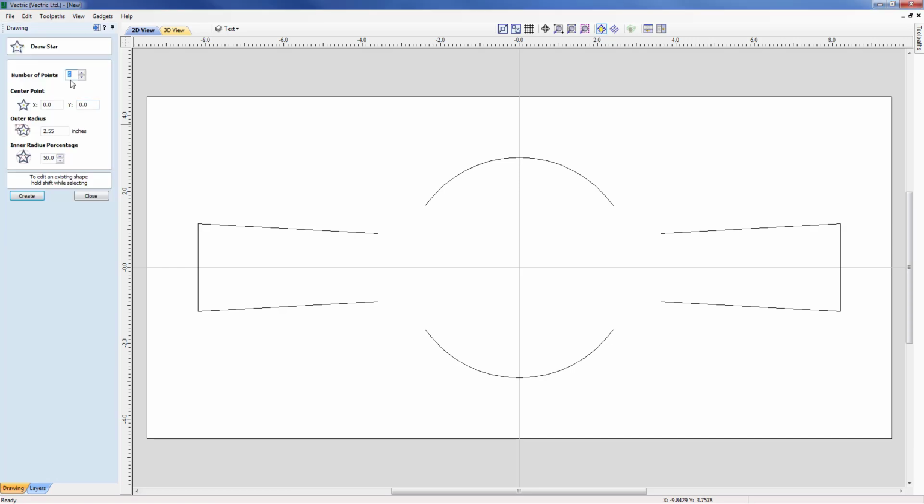We're presented with a form where I can add the parameters, or I'm just going to go to the screen, left mouse key, and just grow the arc now and just drop it in that position. Come across to the form, which now has those values, and I'm going to specify just a smaller outer radius of just 0.5 and apply that.